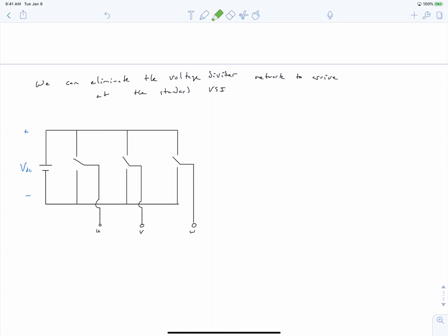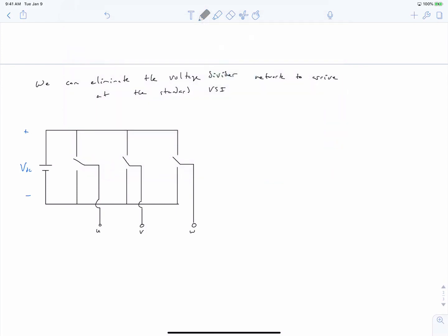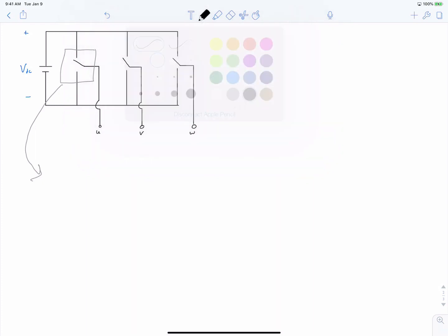And if we focus in on the single pole double throw switches that we've drawn here, so if we draw an exploded view of how this is actually implemented, then a voltage source inverter is going to be implemented with the semiconductor realization for a positive throw voltage but a bidirectional throw current, or a bidirectional pole current, just like the bridge converter was implemented.